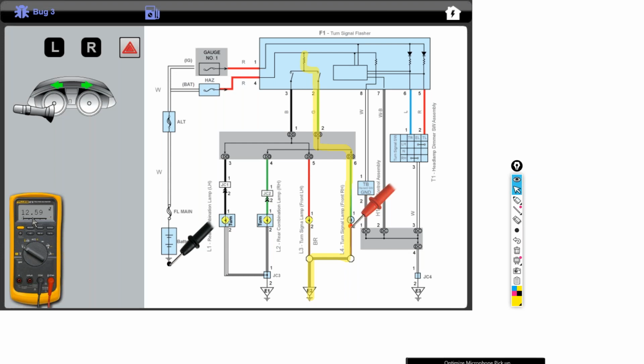So yes, but being that we have full source voltage, we're getting 12.59 volts there. Same voltage we're getting on the other side, so we're getting source voltage on the ground. That would be completely open. But yeah, if we had like 12.2, they could have very high resistance. But 8 volts, 9 volts, whatever would be high resistance on that ground circuit. Okay, is there any other questions?